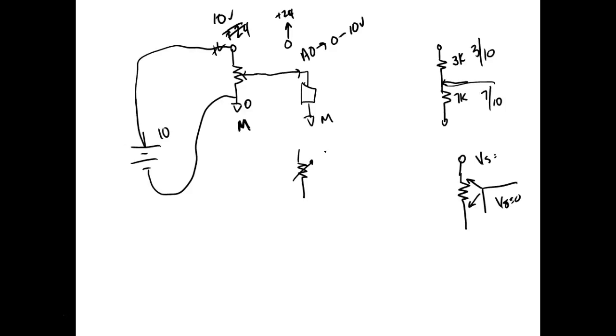So yeah, I could bring another power supply. I could set it up here. I could set it to 10 volts. I could hook my pot. I could take the top of my pot instead of hooking it to my L, hook it to the positive on the power supply, and then set it for 10 volts, and I wouldn't have any error, right?